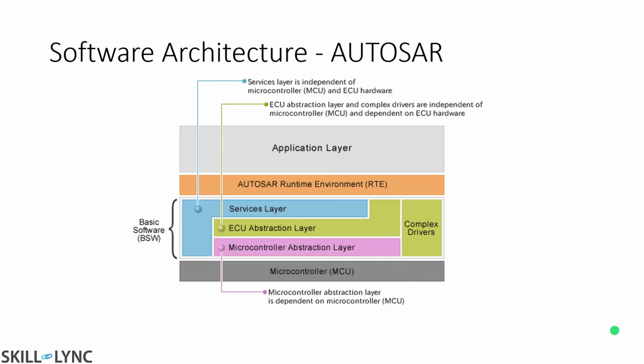So it's going to determine all the memory requirements, so whatever software, all the diagnostics, and so on. And then the runtime environment is going to be the interface between the application layer and the software. So the basic software we can see here is the services layer, ECU abstraction, microcontroller abstraction layer, and the drivers. The runtime environment is going to be the interface between the services layer and the application layer. The application layer, or the software of the ECU, is just going to be an interconnected system.